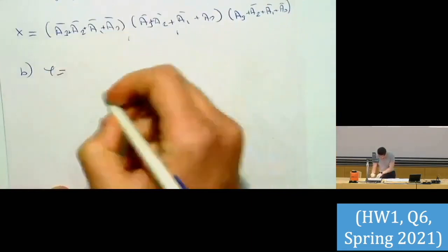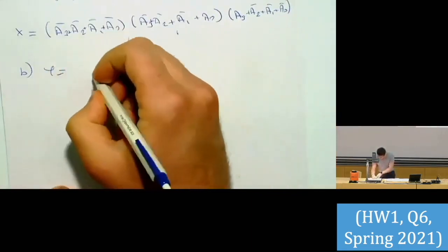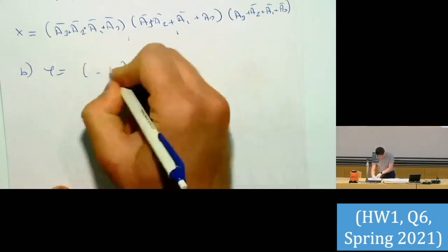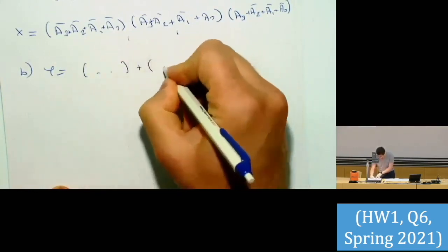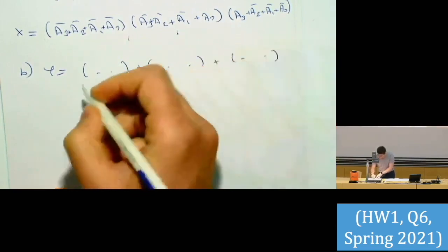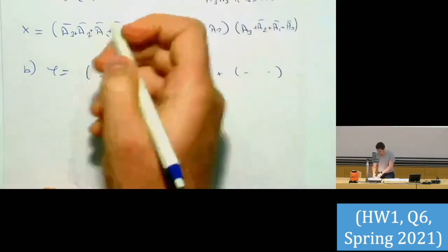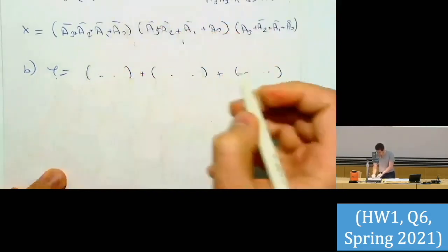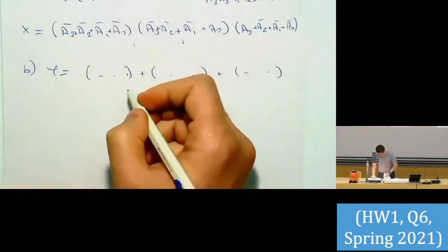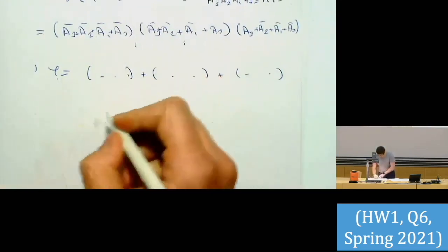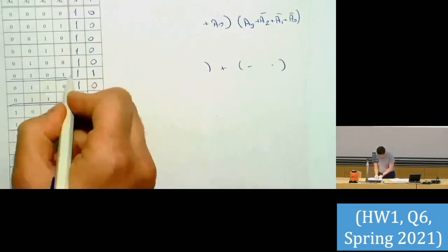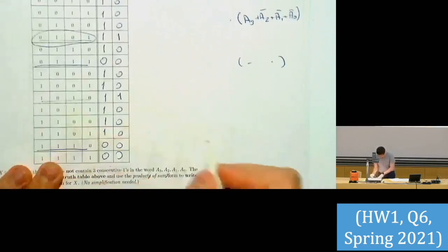So what sum of products is, basically I have terms, those terms are ANDed inside, and outside those are ORed. Right? So, in other words, Y is 1 if one of these is 1. So let's write it that way. To make Y 1, I have two options, either that or that.